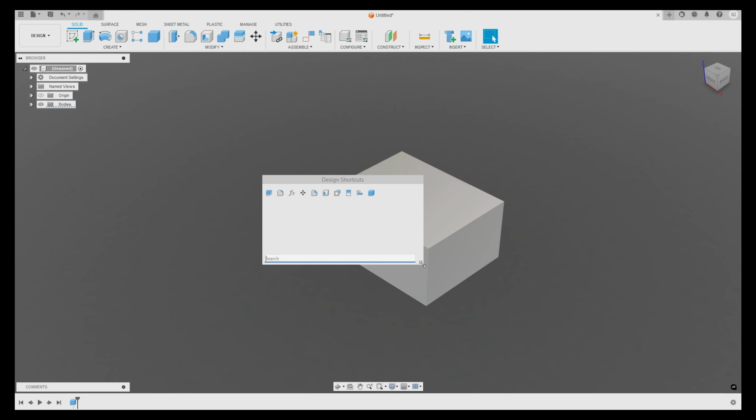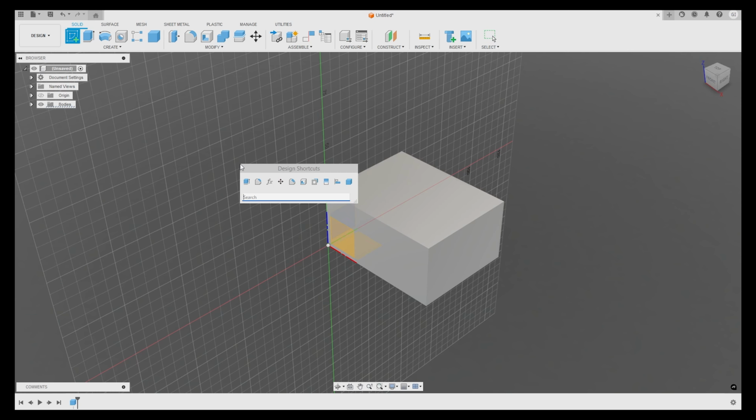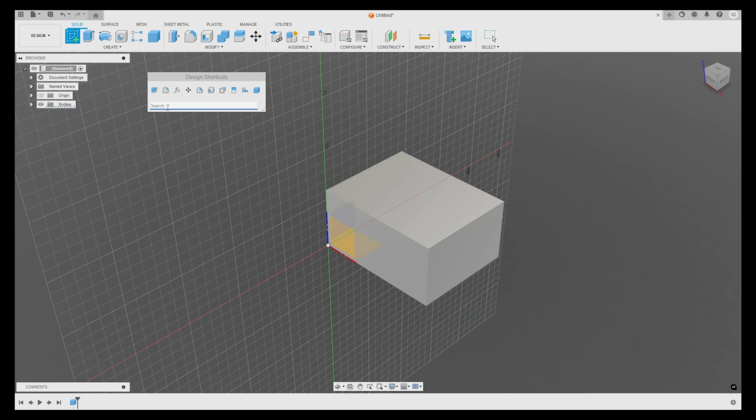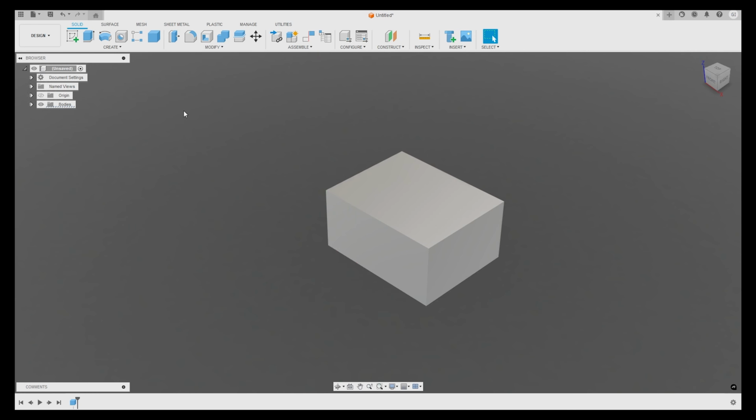The Shortcuts menu is also available in sketch mode, and there we can add all kinds of sketching possibilities. So that comes in very handy. Within the Shortcuts panel, there is also a search panel when too many items are in, so you can again quickly search for example, extrude. If you want to reset all your modifications on toolbars, just click the right mouse button and select Reset All Toolbar Customization.